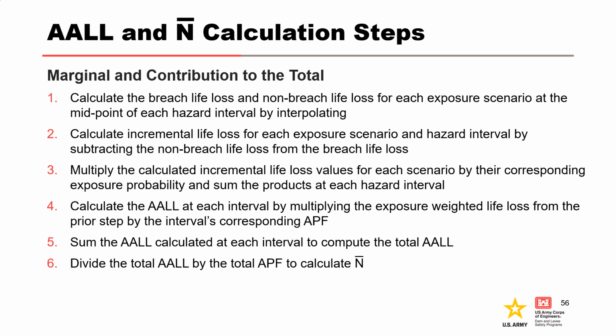Exposure is a fraction of a period of time for which a life loss estimate applies. Typically, we only consider day and night for exposure, but as discussed in Module 1, other scenarios can be considered as well and should be considered when they might impact the risk estimate. To calculate the average annual life loss, we're going to multiply the annual probability of failure by the exposure and incremental life loss, then sum the results to obtain the average annual life loss.